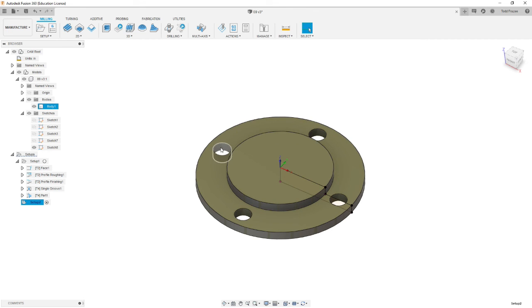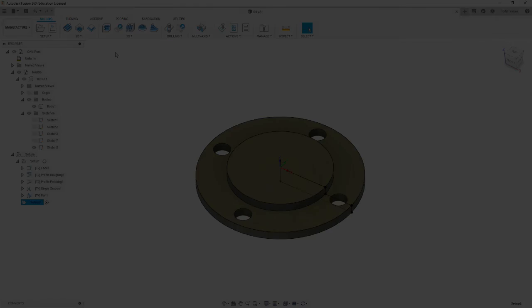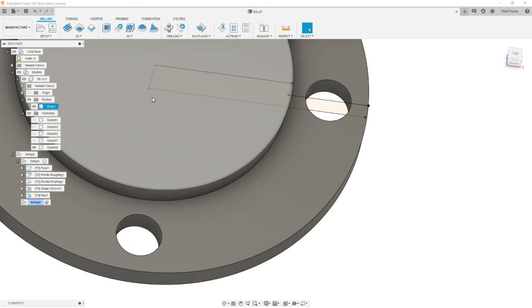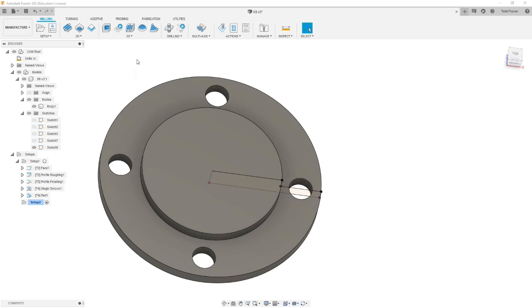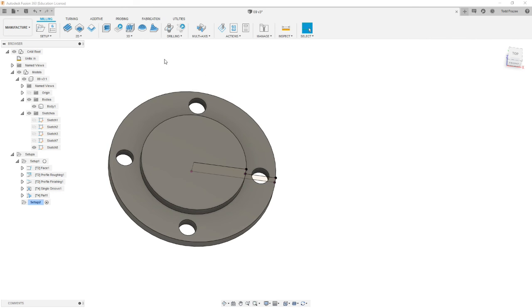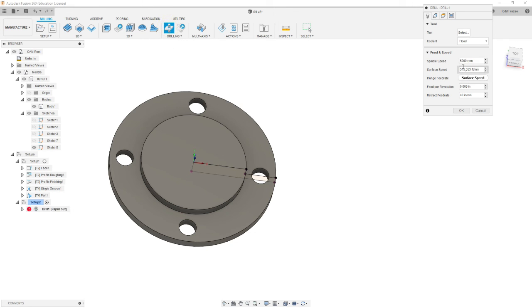And now, if we have a 2mm drill, we could use that, or you could use a circular interpolation with a 1/16 end mill. Okay, so our last operation is going to be to drill these 2mm holes on a mill. You have to have a fixture to locate them. We've created our setup. Now we're going to go to drilling.